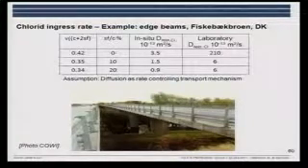And at that time, they chose to have edge beam elements. The road directorate has actually changed the setup. Now they are casting the edge beams together with the rest of the structure, and then they're using stainless steel to hinder reinforcement corrosion.